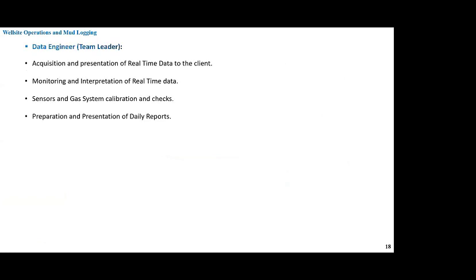The most important and the top position at the mud logging is the data engineer, team leader. He's responsible for acquisition and presentation of real-time data to the client. His main responsibility is drilling operations monitoring. So he monitors and interprets real-time data using sensors and gas system after conducting the required calibrations. Also, preparation and presentation of daily reports, mainly operational reports and the calculation of non-productive time, as we'll see